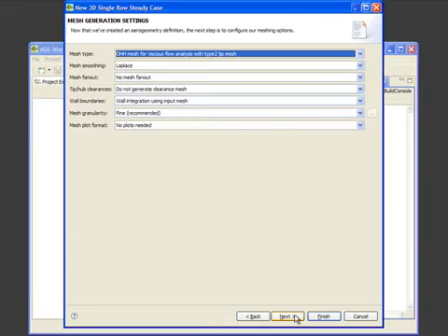Now that we have the aerogeometry data defined, let's change some mesh settings. The mesh is very important when it comes to aerodynamic simulations. It will define the performance with which the computation completes and the accuracy and precision of the data that is output. The first thing to look at is the mesh type.